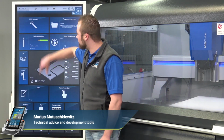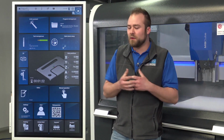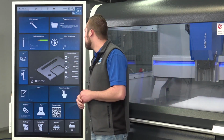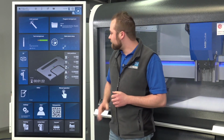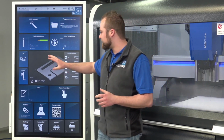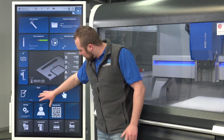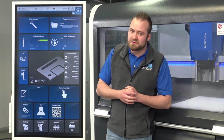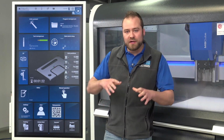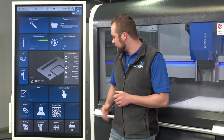On the top we have the main points that you have to use for the normal working on the machine. That means program management, tool management, and also the workpiece setup. Here in the middle we have the machine information, X positions, and also the status of the machine. On the bottom we have the programming part, so the editor, and also the manual operation that you can use for a single hole or doing some easy things.